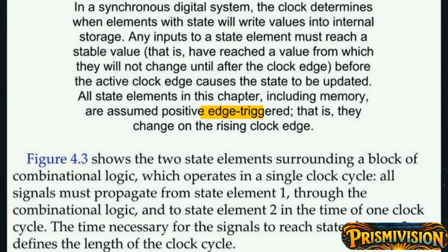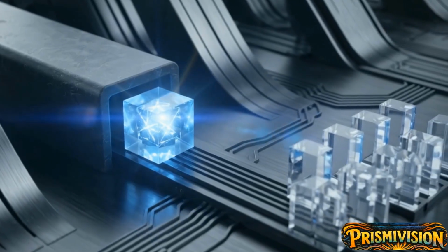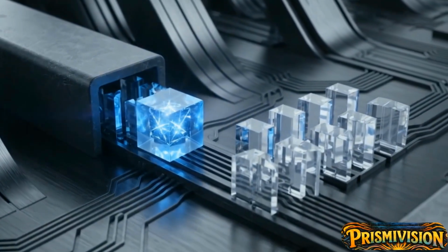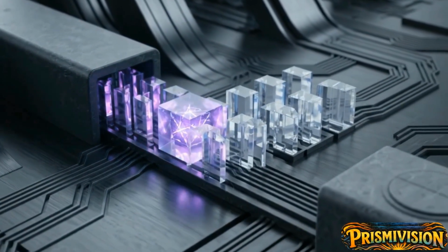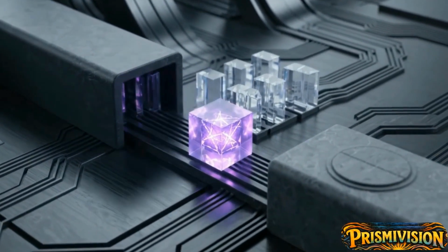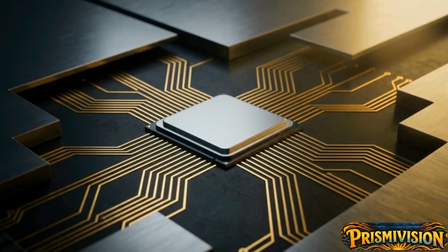As the text explains, edge triggering resolves this potential conflict. Because state elements only update on the clock edge, the system can read the old data and prepare the new value in the same cycle, without the signals bleeding together. In motion, this creates a synchronized loop. Data is modified by logic gates and securely caught by the next register exactly when the pulse strikes. By controlling these microscopic windows of time, engineers created the predictable timing required to build complex, reliable computing systems out of raw electricity.